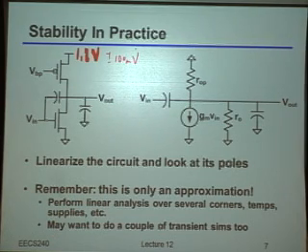So I would argue that even if that's the case, you should still check that the circuit is stable with, as an example, a 300 millivolt power supply, 400 millivolts, 500, 600, and so on and so forth. Anyone know why I say that? Why am I claiming that you should check it even at numbers that are way outside the spec of what your nominal supply voltage is supposed to be? It's a little bit of a trick question.